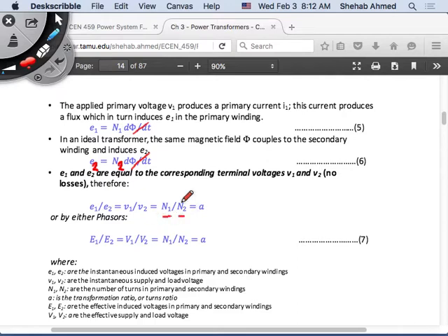And because we put a voltage, and this voltage is what we see around the coil at the core, and we ignored any impedance here, or the resistance of the copper wires, for now, then this V that we put here is equal to E, right? So for now only. For the ideal transformer, V will be equal to E. So that's why we said V1 over V2 is equal to N1 over N2 is equal to E1 over E2.